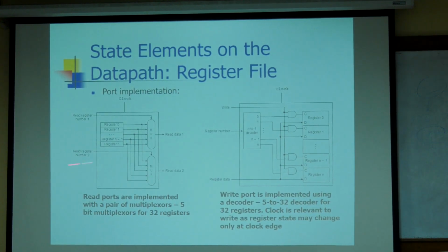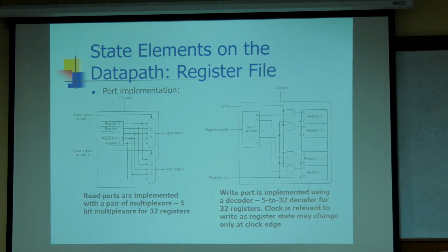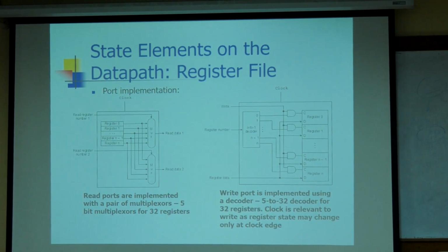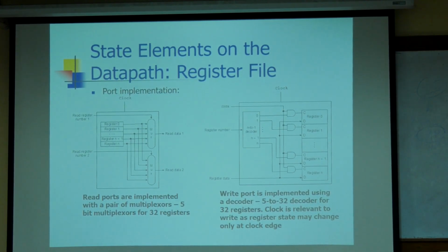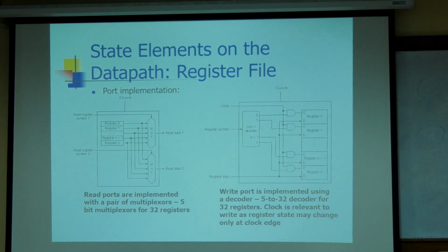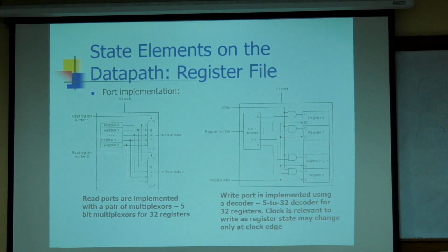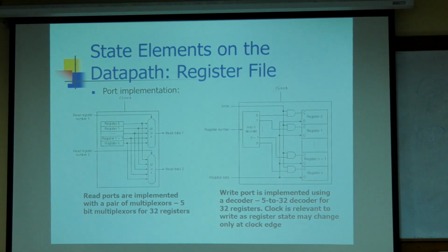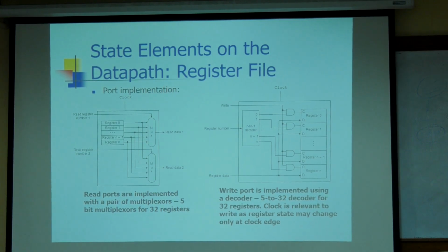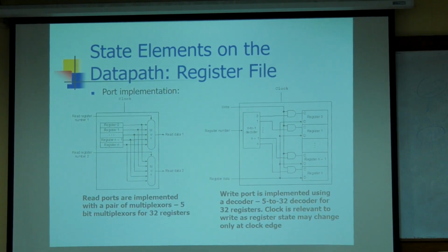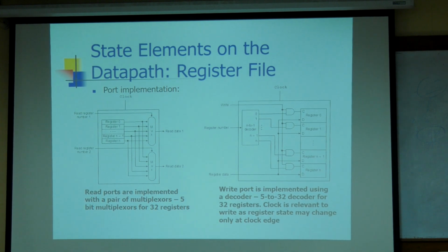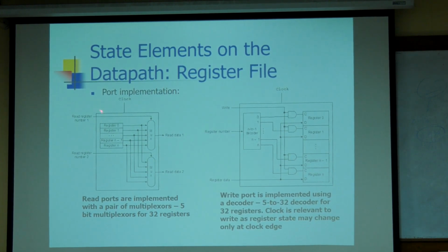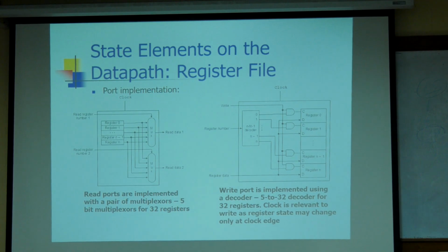Then you see, the design is simple. Register creation is simple, very logical. You can write it easily in just one line: input assigned to output at clock equal to 1, or on the clock rising edge or falling edge, the input will be assigned to output. That's all, only one line of code. Writing a 32-bit register in Verilog is very simple. So we can create the 32 registers like this.